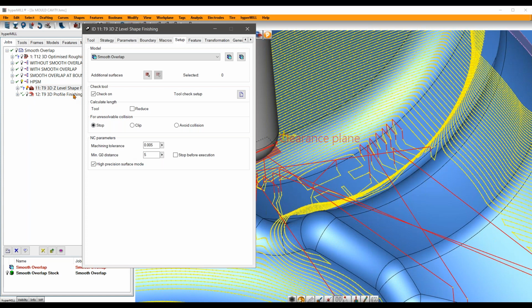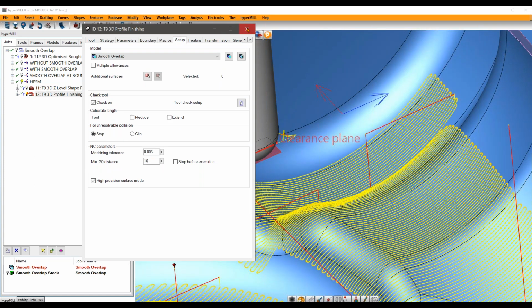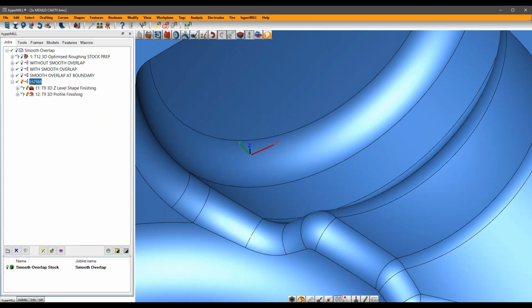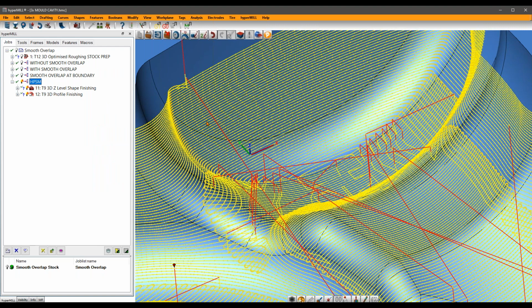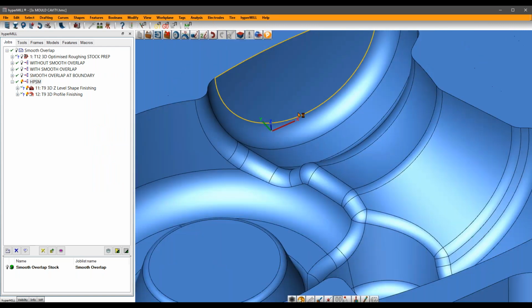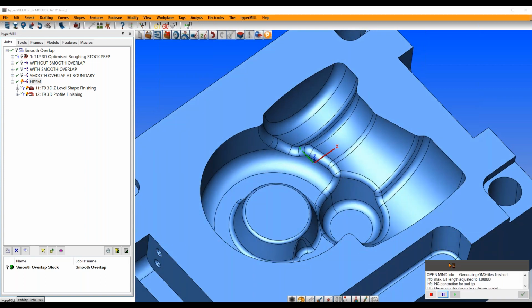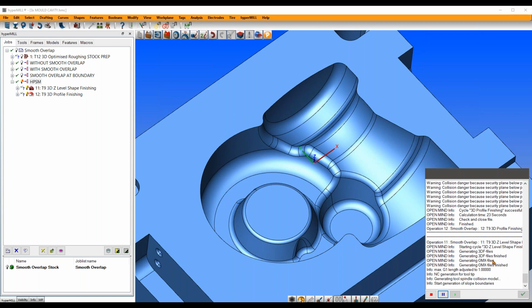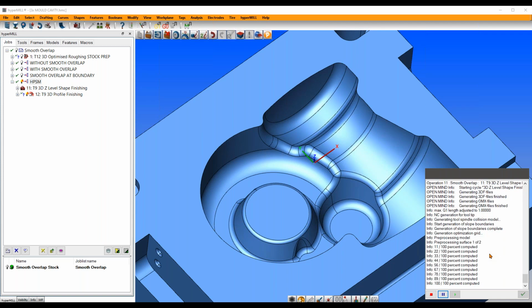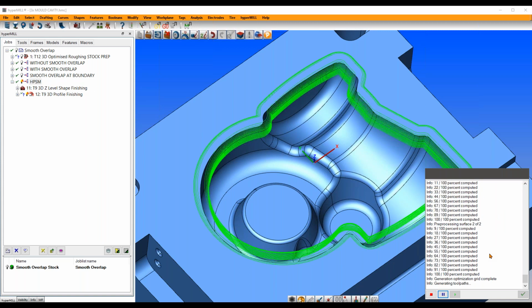it's just a tick box exercise. Turn it on and calculate. It shouldn't take too much longer to calculate this area. What we start to see is in the calculation window, adjustments and how many points it's treated, how many points from the tessellation, the polyhedron, compared to the true surface mode, it's adjusted in order to perform a better surface quality.